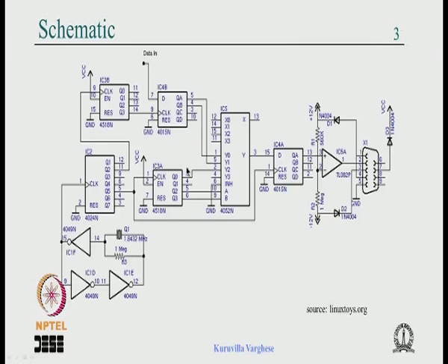It just shows the symbol and the interconnection between the ICs, and it does not give you the function of the circuit. Many times you have to refer to the data sheet of each IC and try to understand the internals. In simple cases like gates, it will be simple, but if there is a processor, one has to read the data sheet of the complete processor to understand memory, processor, gates, flip flops, everything. Sometimes a design description needs to be written saying that this is a particular IC, this is the function of that IC, and so on.